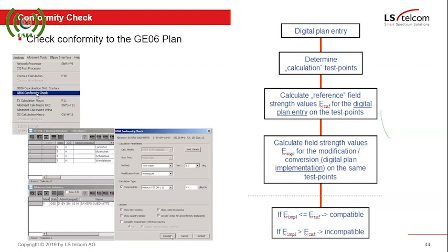So obviously, we've also seen that with transmitters 67 kilometers from one another, with a guard interval of 1/8, there we had very, very little areas that experienced interference, because it's normally further than 67 kilometers. And then your signal has deteriorated in level so that you overcome your protection ratio and you've got coverage without any synchronization problems.